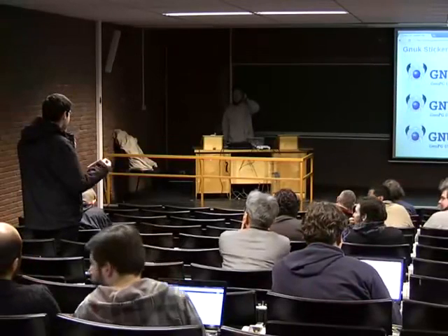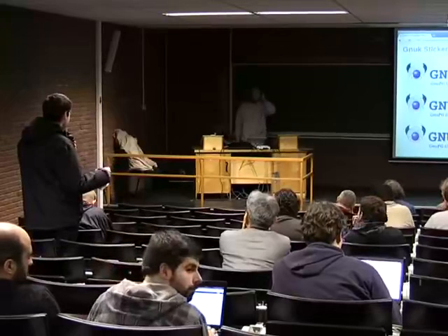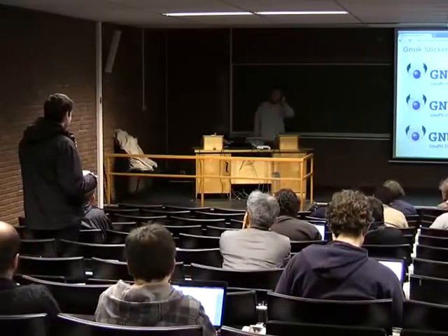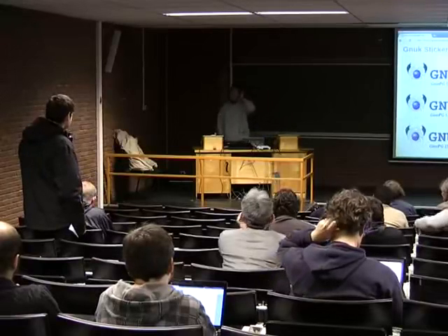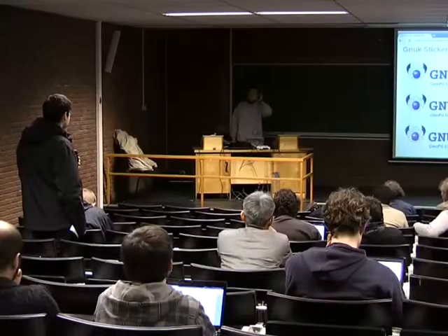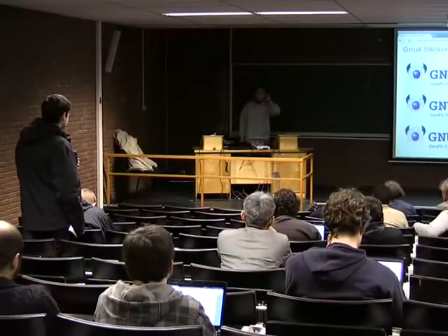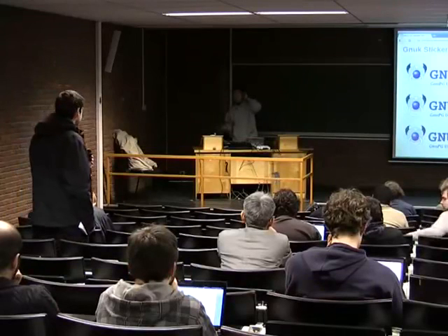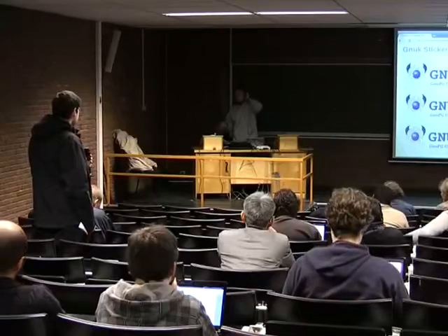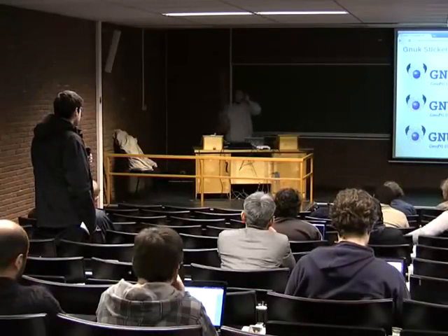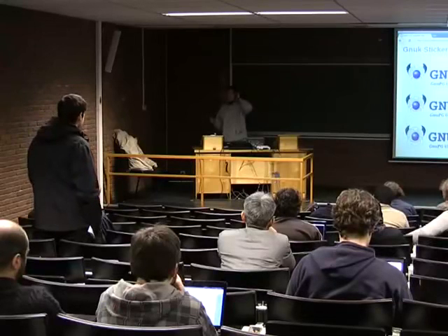And another question is about generating a key directly in the device. You mentioned it's not supported at the moment. Is it because of lack of enough entropy? Yes, you are right. At the beginning I considered like that, but we need enough entropy for ECC. For RSA, we don't need a true random generator for computation of digital signing or decryption, but it is needed for key generation. So at first, I didn't support key generation, but for ECC support, we need a true random generator. So last year, I implemented my own method for a true random generator.